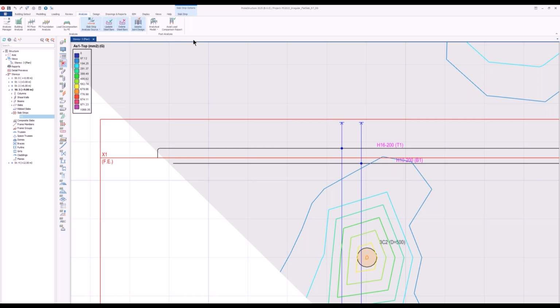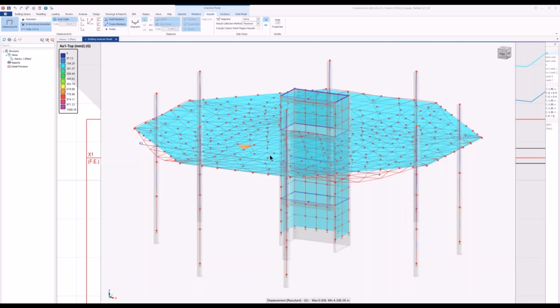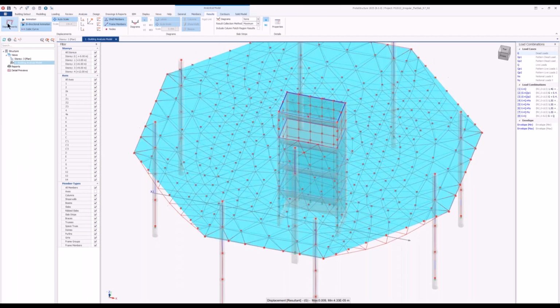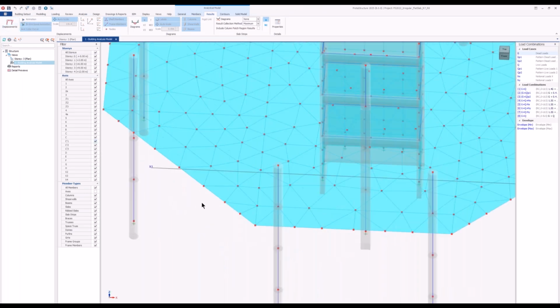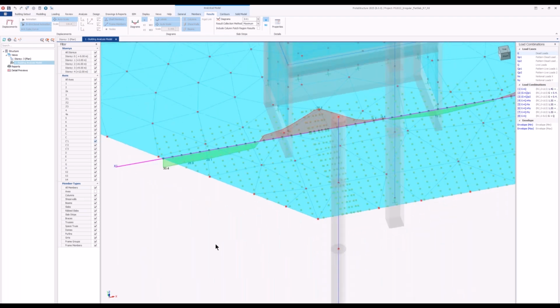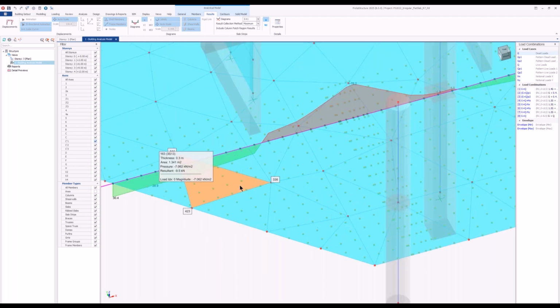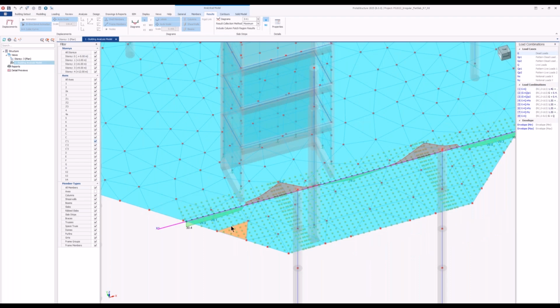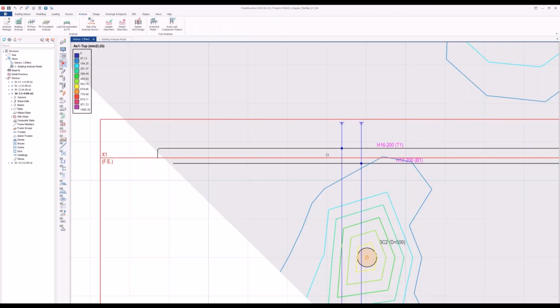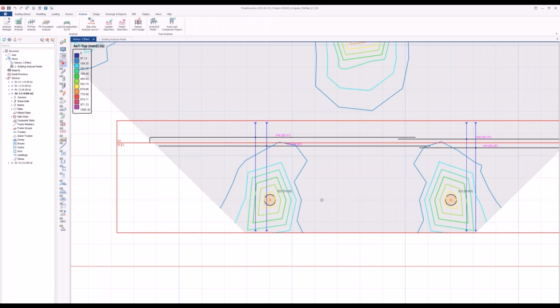And also let's check the analysis results. Let's get rid of the displacements here. And if you check the moment profile of the slab, you see the station points that this finite element strip is collecting results. So from these small dots, we are collecting the results and making it ready for the reinforcement calculation. Okay, so in the tributary area from these stations, number 16 bars are calculated at the top.